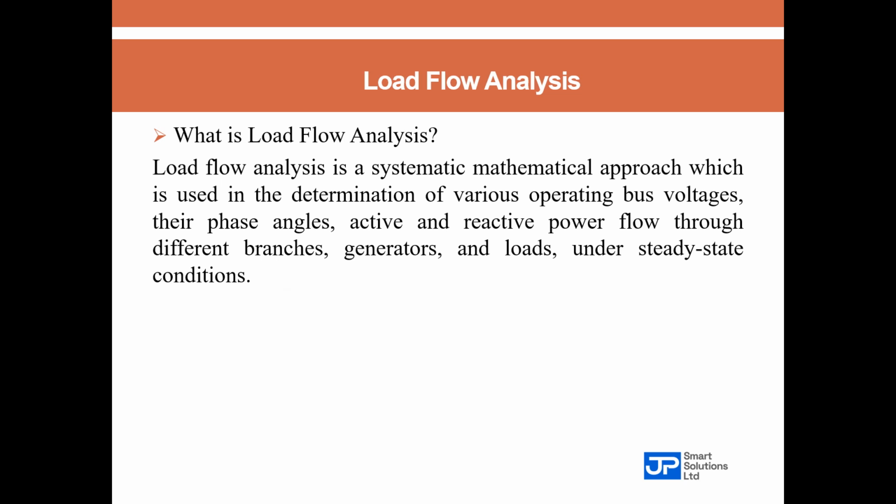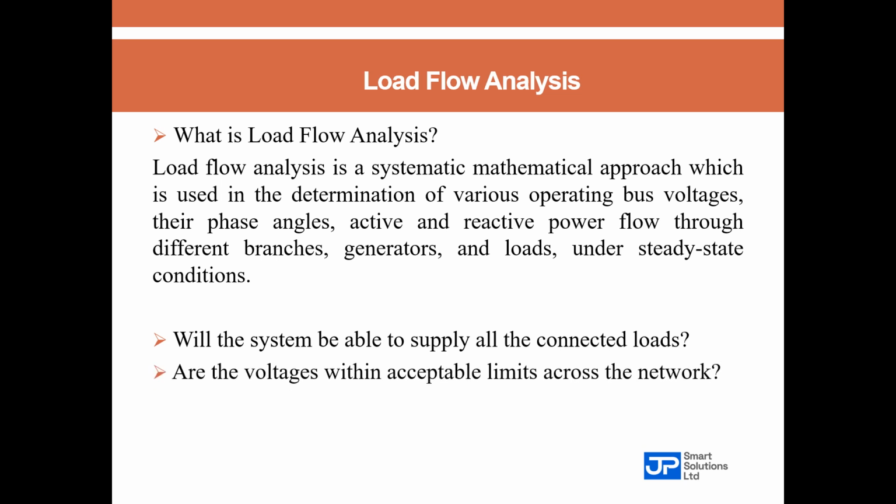Now, load flow analysis answers critical questions such as, will the system be able to supply all the connected loads, or would there be need for an improvement to the system? It answers questions like, are the voltages within acceptable limits across the entire network?